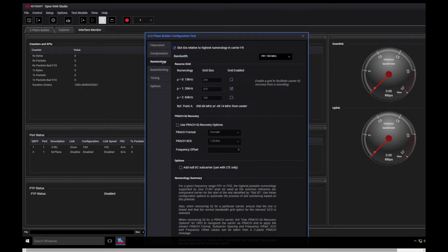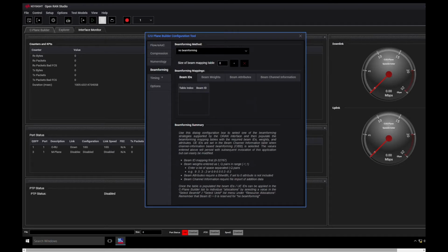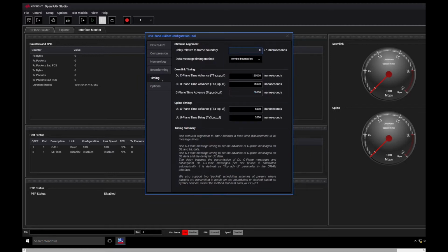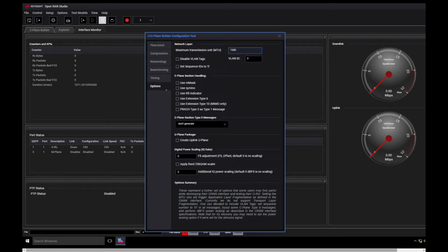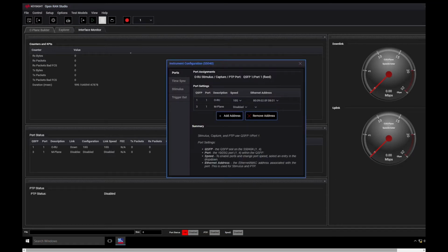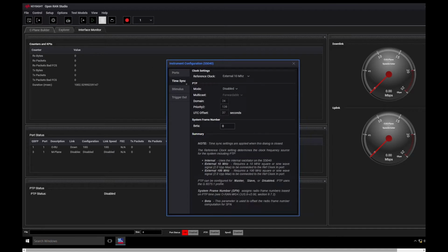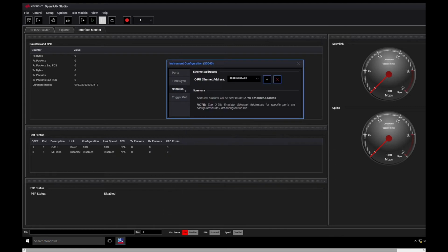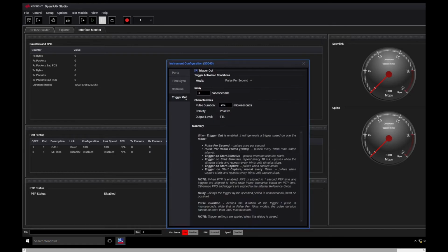Parameters such as component carriers, subcarrier spacing, antenna stream count, TDD configuration, delay management, CU plane transport, digital power scaling, beamforming, IQ compression, and S-plane are some examples of what we can adjust. The O-RAN architecture requires various synchronization needs, which include Precision Timing Protocol, PTP, and Sync-E, which is synchronous Ethernet. The O-RUs are separated from the O-DU and O-CU, so timing and phase must be aligned for TDD and FDD